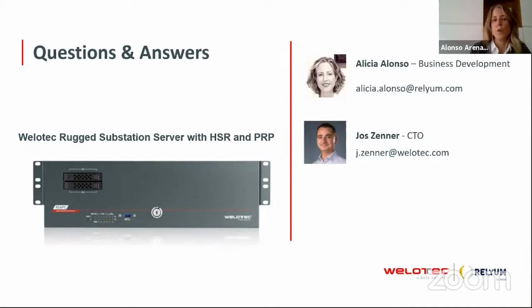So I consider 1 millisecond for the packet to get to the protection, one more for being processed, and one more for opening the controller. So there are protocols focused on low latency applications, and this is one of the reasons why they are mainly implemented in hardware, in a special technology in FPGAs.